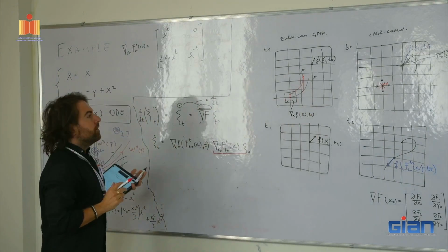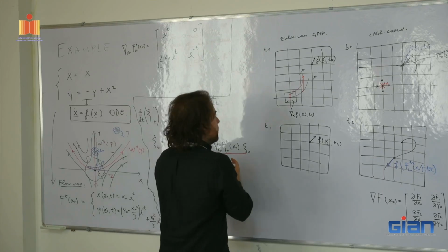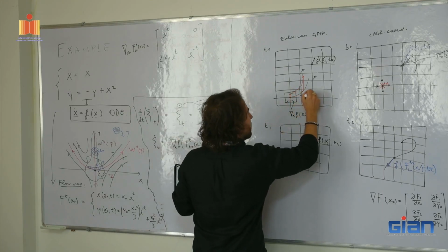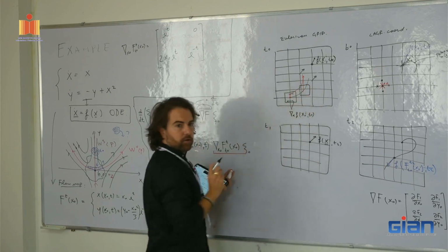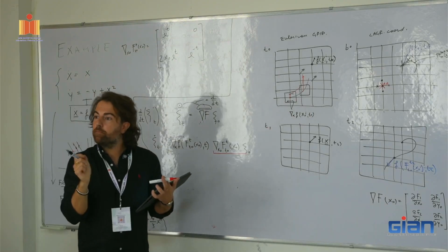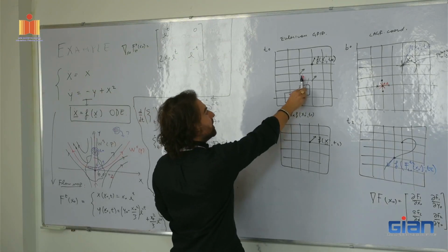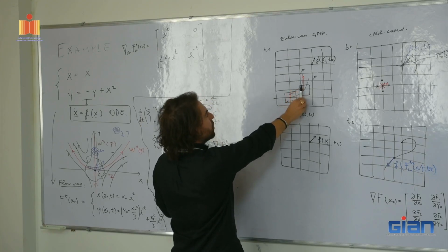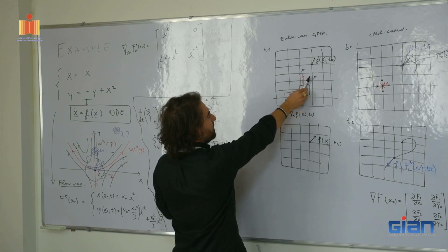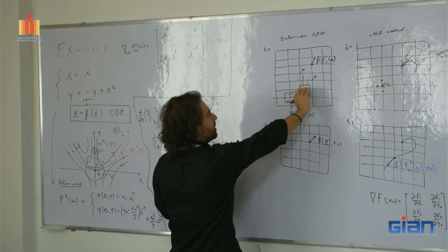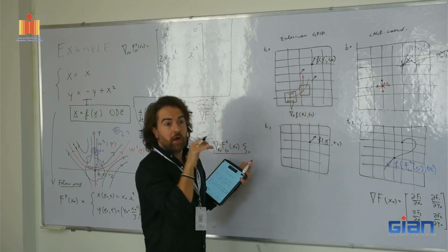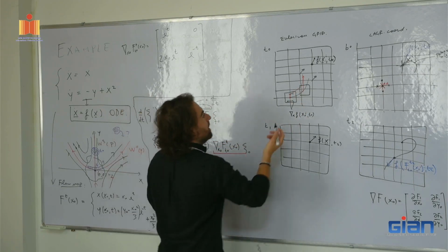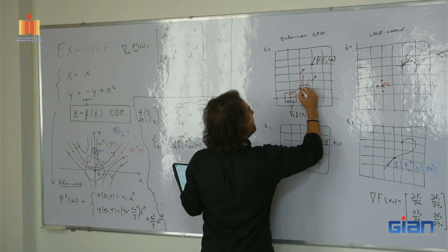Now you have to sample the velocity Jacobian at this new point along the trajectory. But it's very important also with which orientation you arrived here, because the velocity Jacobian here is going to depend on it. If I'm a fiber in this direction, or this direction, I'm going to feel a different velocity. So let's say, for instance, here I would have a velocity field that does that.